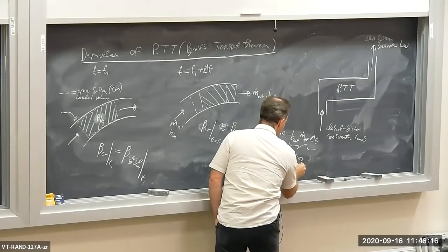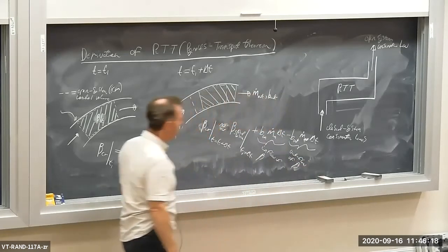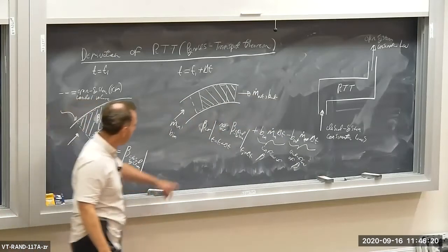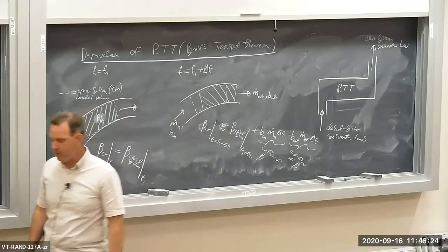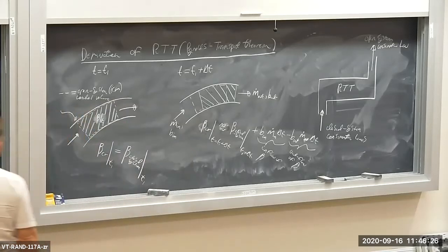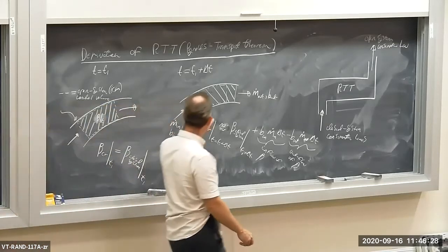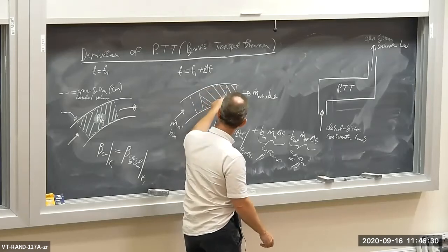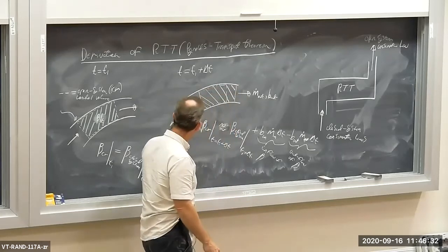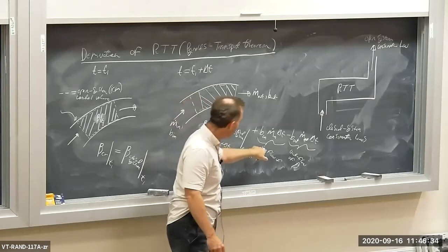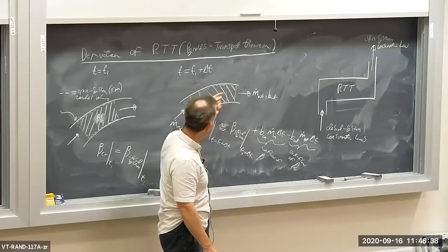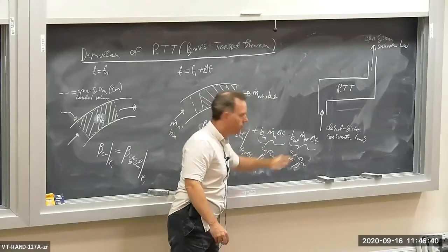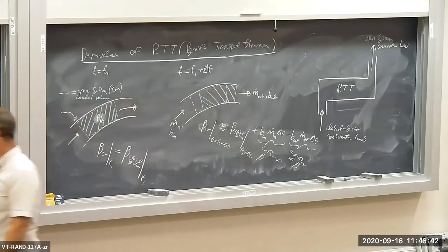of beta. So let's read this in words here. The amount of beta within my dash control volume, my open system, is approximately equal to the amount of beta that's in my closed system, that's the crosshatch, plus the amount of beta that's flown in due to the mass flow, minus the amount of beta that's flowed out due to the mass flow, okay?